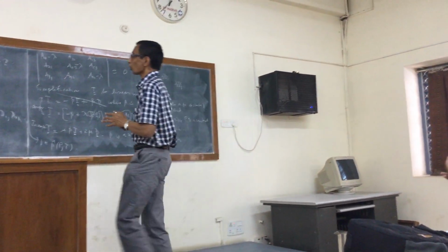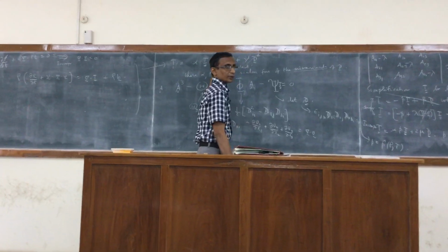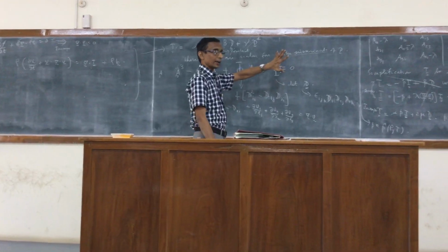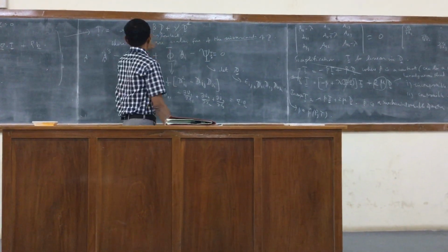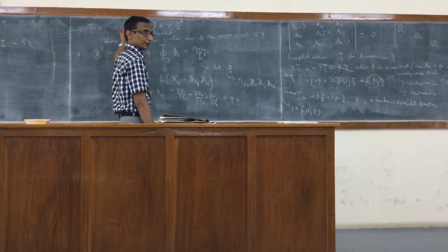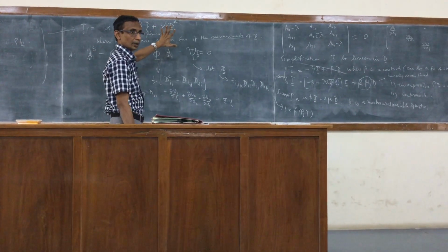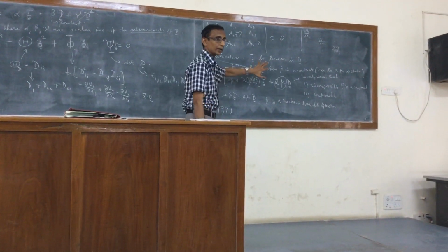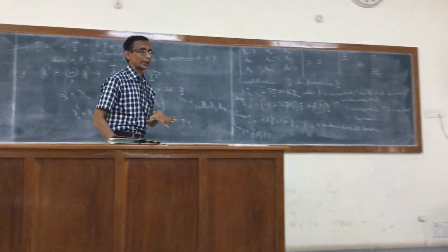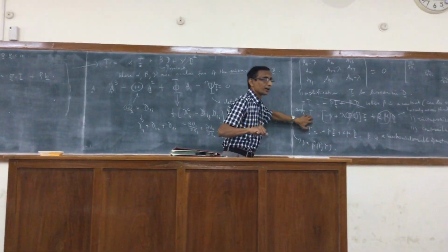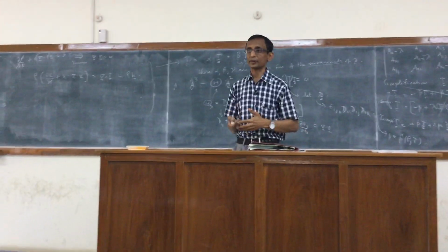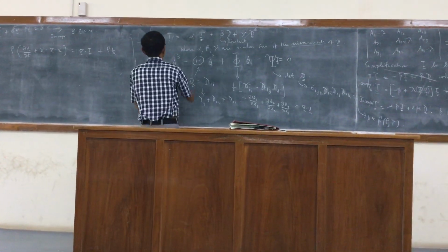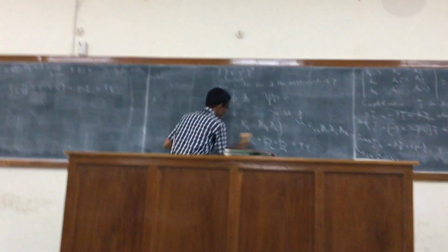No, because we are looking for the most general form consistent with the Stokes hypothesis, which turns out to be this. Now I am imposing that T has to be linearly related to D. So alpha can, in general, depend on all the invariants of D, but for something where T has to be linearly related to D, it can depend only on the trace. So this is only for what is called a linearly viscous fluid. So we finally arrived at what we are going to use, and that is